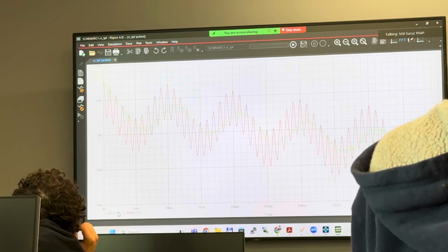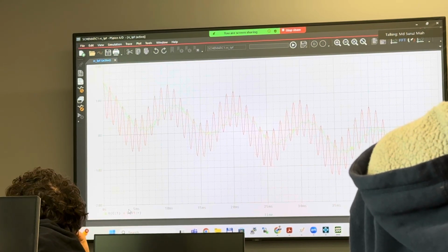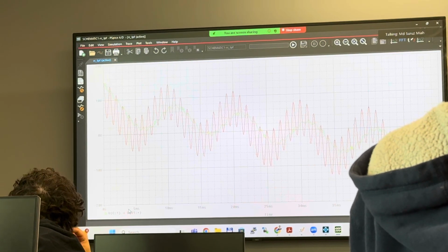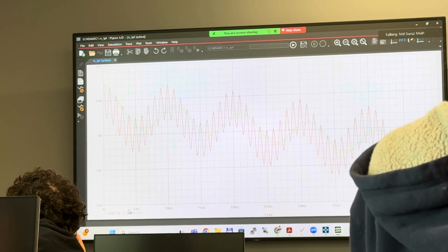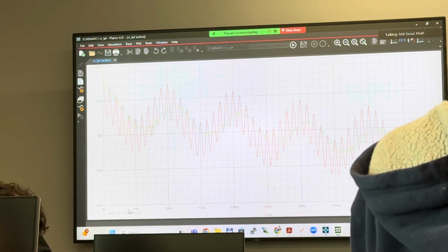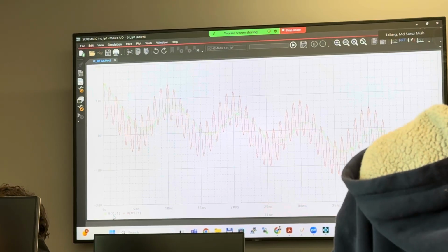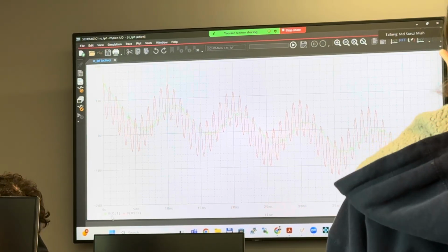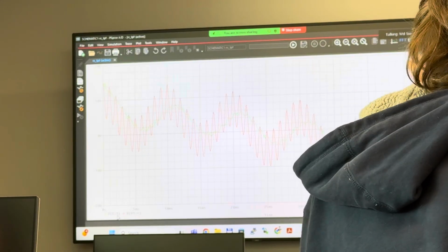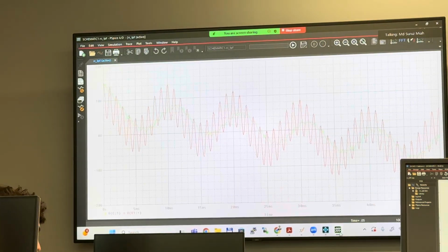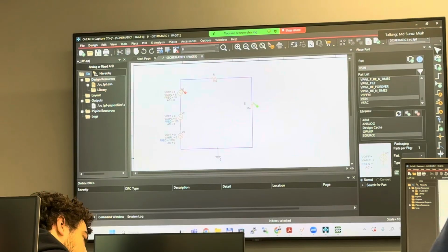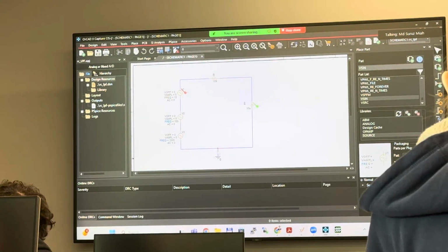So from terminal 1, that is why, guys, I mentioned the terminal. The pin number is very important. That way you know where you are taking the voltage from, the signal from. So you are seeing the voltage of the capacitor from terminal 1 with respect to ground.